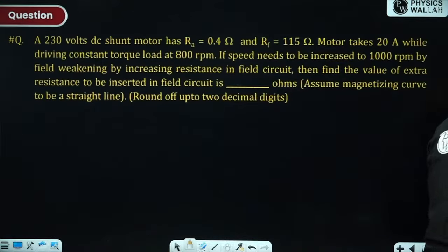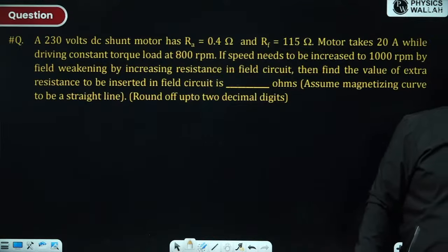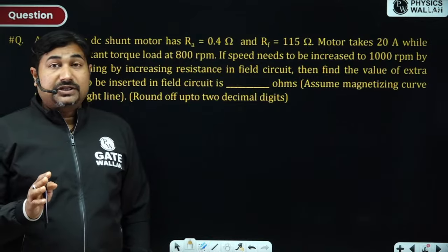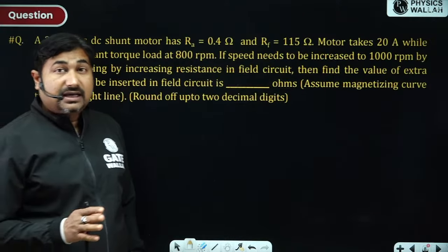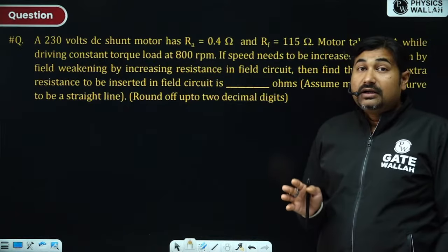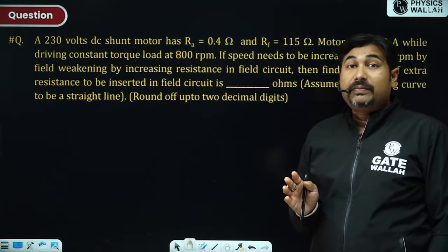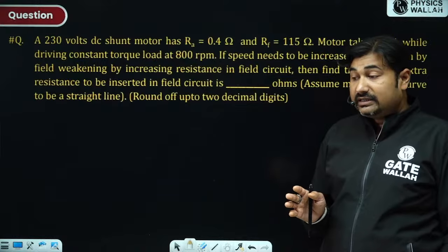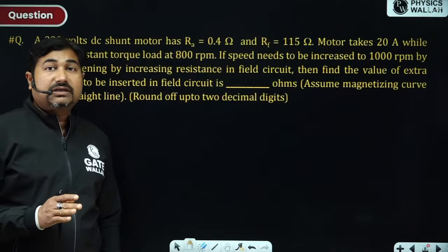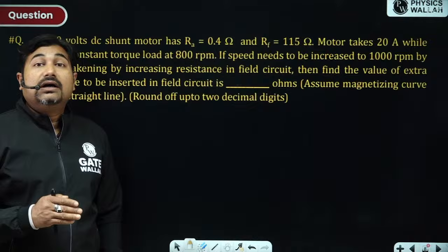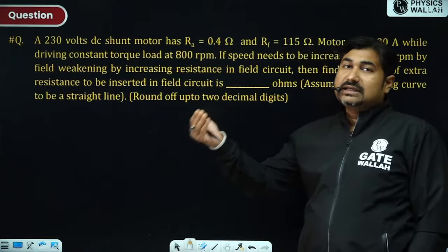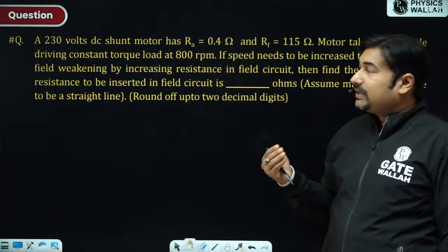Okay, so let's go with this one. Always remember, in case of parallel operation, there is a very high chance this year they may ask some question from parallel operation. So if the question is from parallel operation, always remember you need to convert to a common base while calculating the kVA or kilowatt shared by each transformer. And one more thing, always remember that in case they ask about per unit impedances for proportional load sharing, then those must be on their own base values. Per unit impedances must be on their own base values.